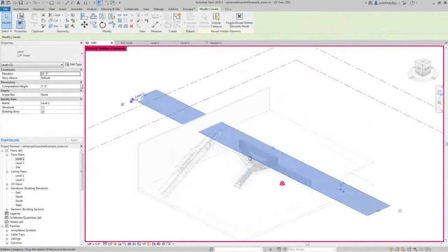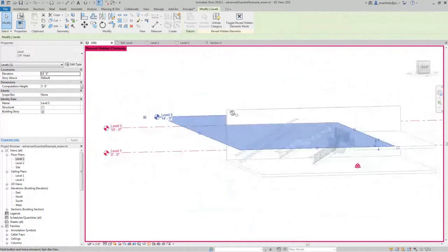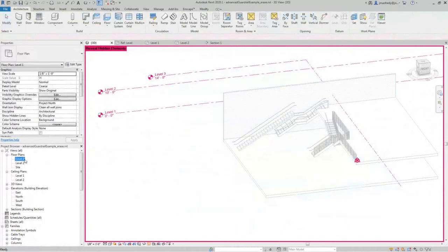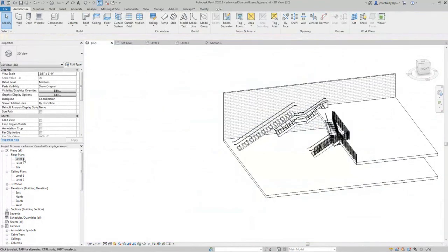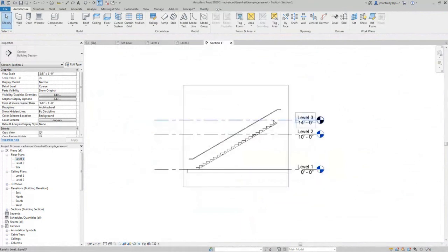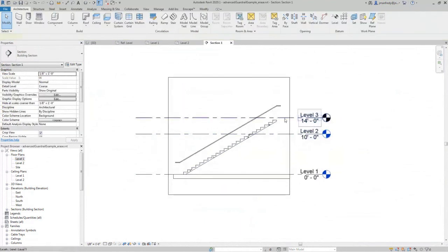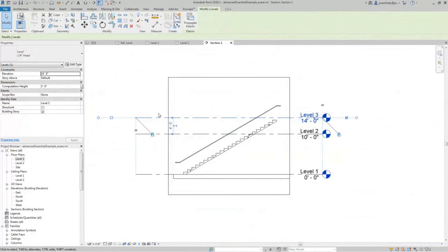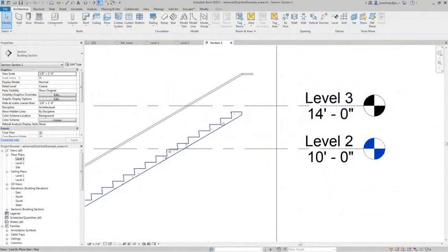This is my level tag. I'm going to stretch it over to here so it's included in this cross section. See, it's like a plane, and I didn't include it in my cross section here. So when I do that, I'm going to turn off this. My tags were turned off. When I look at this section, I can now see that tag show up right there. This is like a plane. The plane has to intersect this box in order to be visible and seen. So that I stretch so I can see it. So you see the stair is going to, this is where the floor would go. And the stair goes up to one riser below where the floor is, or your grade or something.